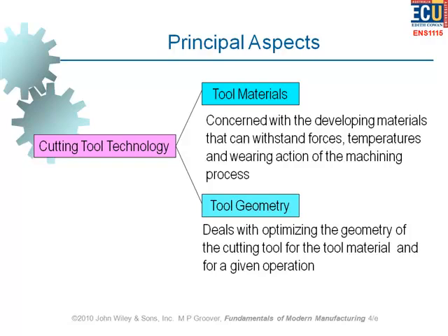What ductility does provide us is actually the ability to deform, which isn't desired in cutting tools. Instead of ductility, we may refer to something else, which is called toughness. Toughness is more important than ductility in cutting tools, which is defined as resistance to fracture. That's important. Okay, what else?